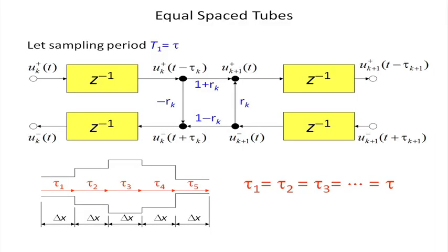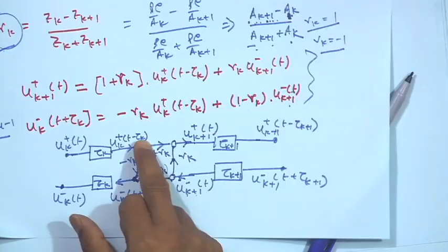Okay. So, next class I want to derive the total vocal tract transfer function for such an n tube model. Instead of a single tube, I consider multiple tubes of different cross sectional areas joined with each other. Let there be n number of tubes, then I derive the signal flow diagram for the single junction. The same junction will be repeated. So, if there are n tubes, n minus 1 junctions will be there.